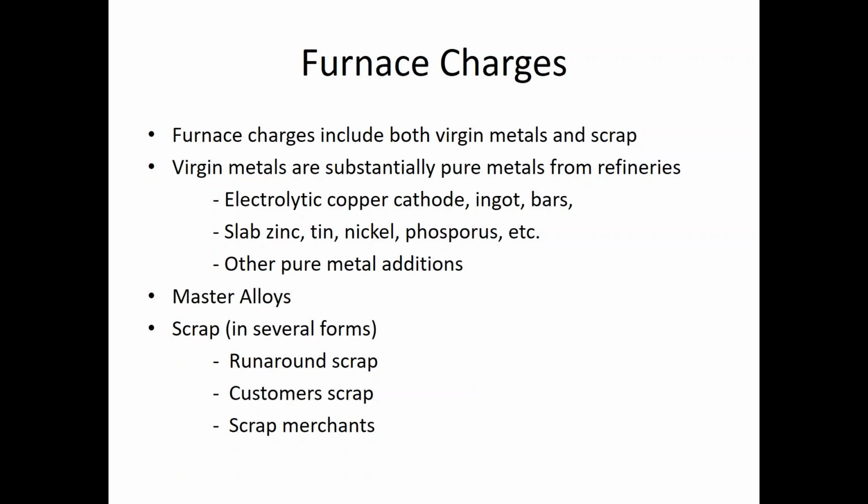It's easier to get it in if somebody else has already made an alloy, maybe highly concentrated, with that other metal addition added. So you just drop it in. It's like dropping pellets into something, and they gradually melt, and then you assay the furnace afterwards.